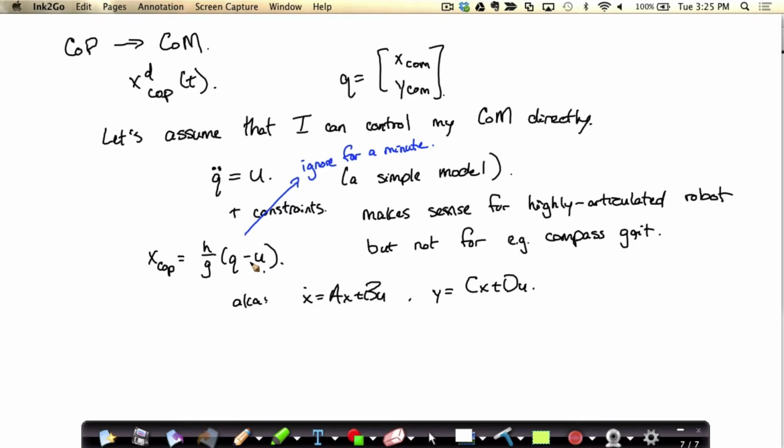Sorry, can you just show us how you got to that XCOP expression? And then also, you switched from Z to Y, I think. Just to clarify. I did switch from Z to Y. No, I didn't. That's correct. Right. So no, it's the same thing. But Z is up, and I said that I can go ahead and think about my center of pressure in both the X direction and the Y direction. With no extra. I could have just left it as XCOM and we'd be fine. But just knowing that it generalizes trivially to solving both of them at the same time is nice.